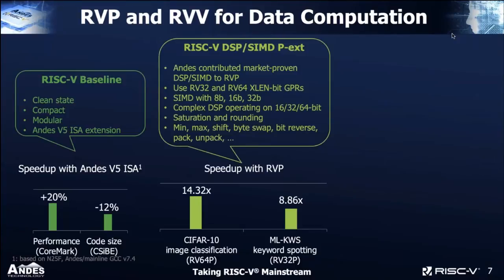Keyword spotting algorithms can increase performance with the DSP by about 9 times. So certainly it depends. Adding more hardware accelerates performance, and usually because so many fewer cycles are being executed, it actually improves power as well.